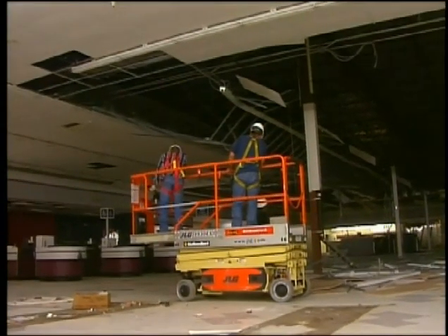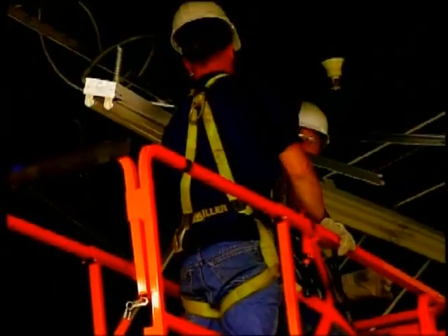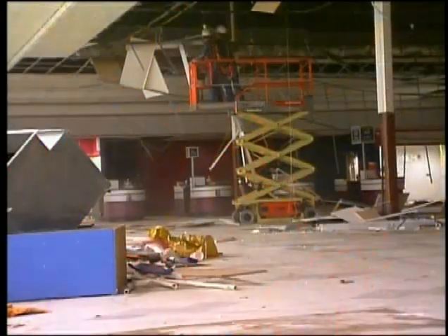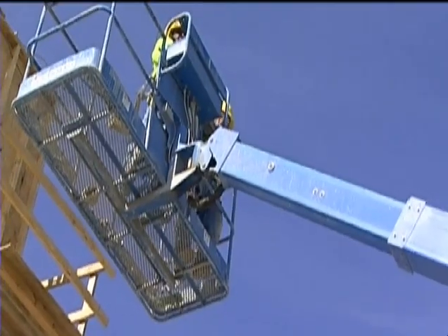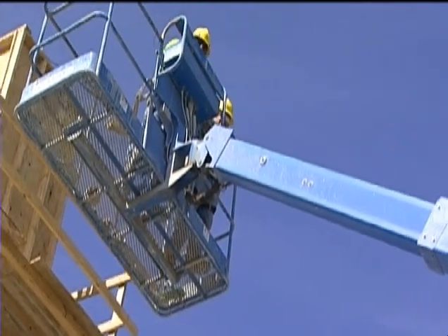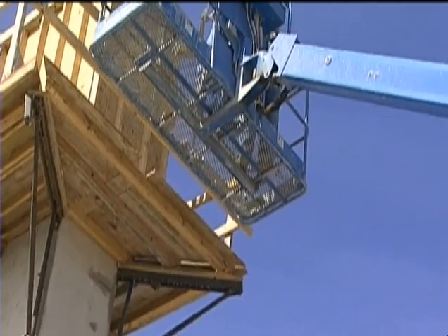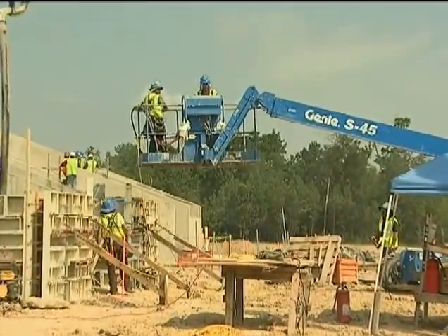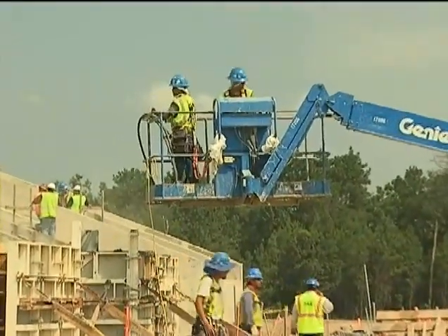Only authorized and trained persons should operate an aerial lift. Never tie off to an adjacent pole, structure, or piece of equipment while working from a lift. Personnel should always stand firmly on the floor of the lift. Never sit or climb on the basket or guardrails, or use planks, ladders, or other items to attain a higher work position. If additional height is needed, then the lift should be extended, or if necessary, a different lift used that is appropriate for the job.